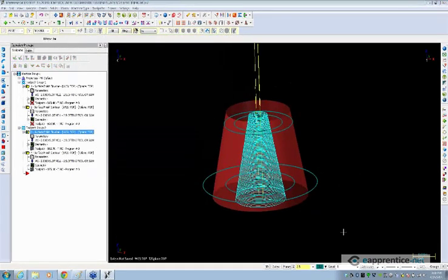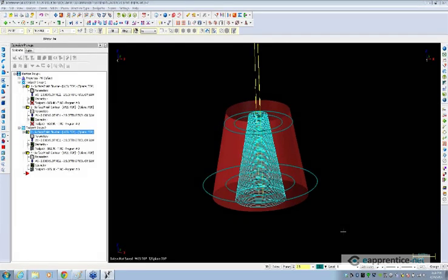Right. Perfect. Okay. We have a great question. Comment coming in from William: Rough Pocket will support undercut tools. You can pick a start point. Tool will move to the start point before cutting the pocket, then move back to the start point after cutting the pocket to change to your next depth. You can also disable roughing passes and just output finish passes. That's coming in from Bill Bentrup from CNC Software, the makers of Mastercam, so we do appreciate that comment, Bill. Yeah, thanks, Bill. That's great to know.